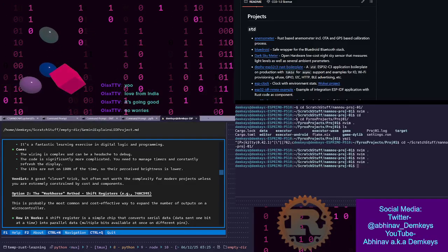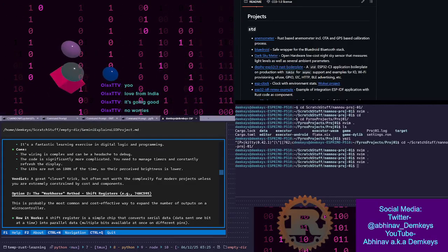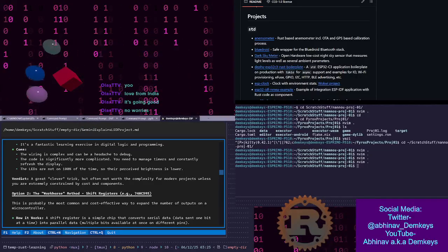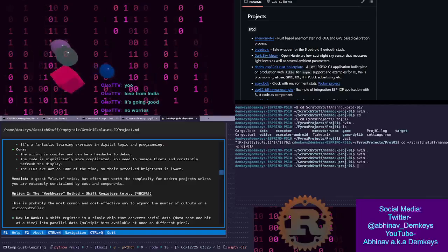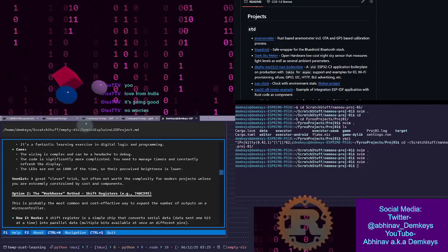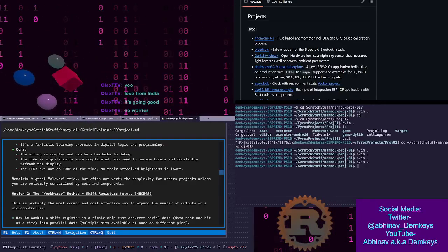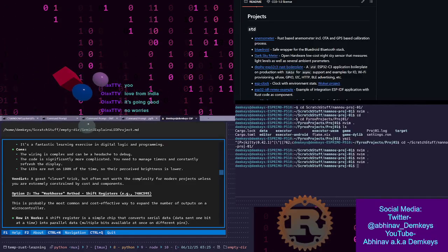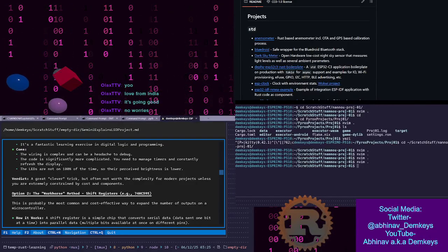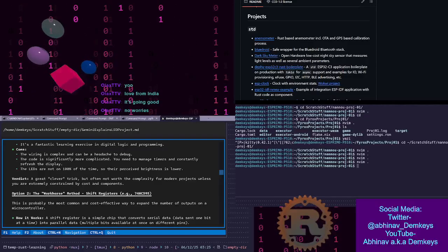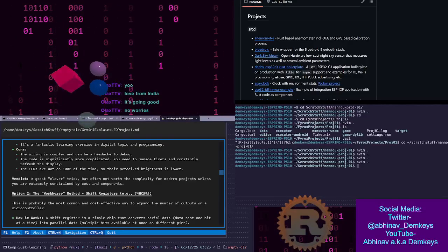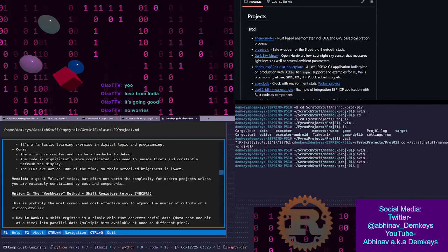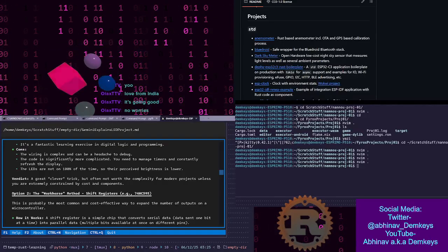There can be any number of complications when you're not isolating two circuits from each other. There's also the fact that if you are joining two circuits together, you need to really understand how both those circuits work in order to be able to properly and confidently join them together, and not worry about, again, something high power powering something low power. Just a second.